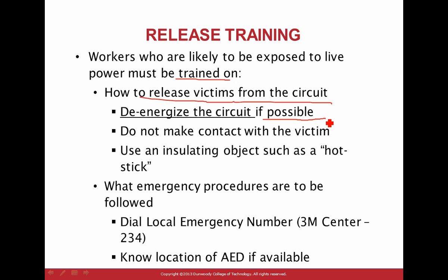So how do you remove the individual from the circuit? That's different from one piece of equipment to another. How do you de-energize the circuit? Part of the debriefing they use, a lot of it related to opening panels, applies to you guys too. You open a control panel, you're going to work on it, you have to debrief and talk to each other, you and the team working on it, before you start. Part of that debriefing is: how can we shut off the power if somebody gets electrocuted? Where is the closest disconnect or emergency button that we can shut down if somebody gets electrocuted? That's so you identify it.